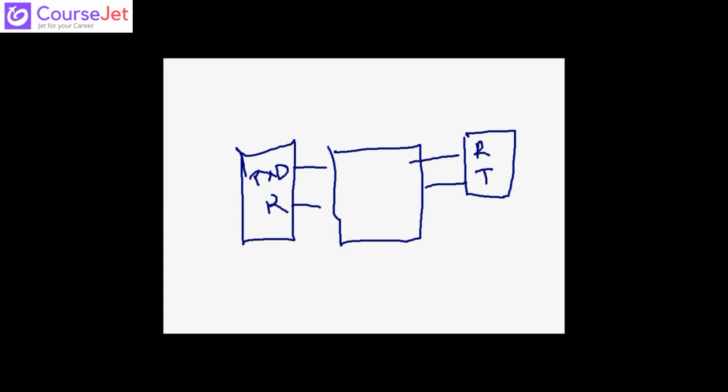These two pins are not directly connected to your GPS module. TXD is connected to RxD and RxD is connected to TXD, but before this communication happens, you will have one converter, and that converter is the MAX232 physical device, as I said. One side is your TTL side and the other is your RS232 side.